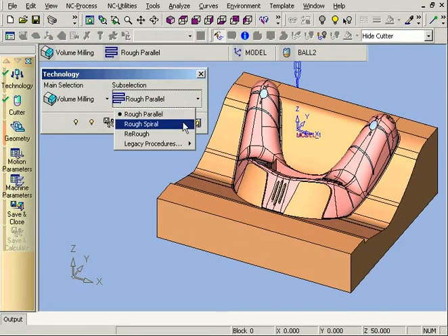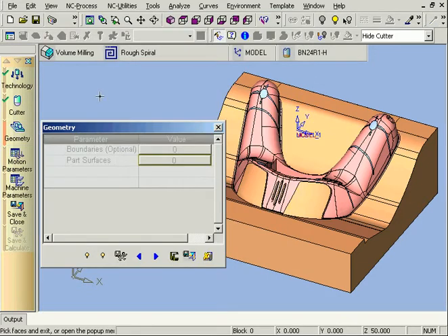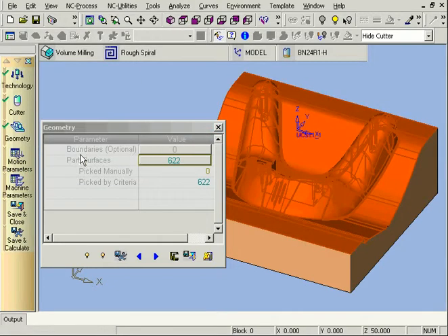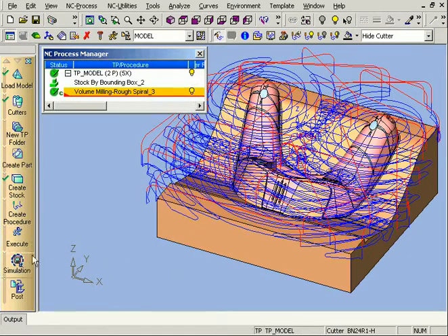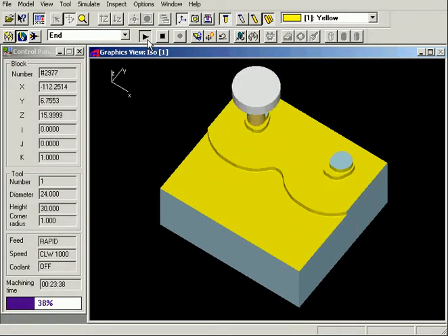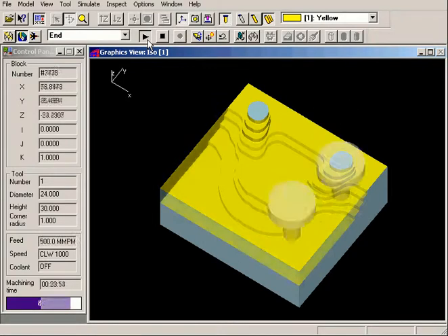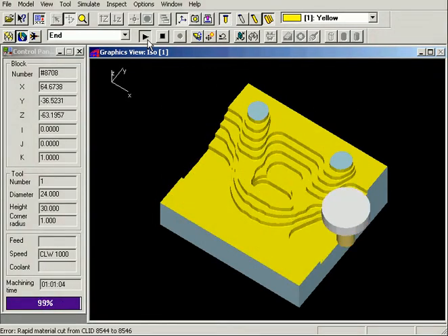The example shown here is rough machining of the entire part. This option allows the system to optimize the machining strategy. Alternatively, it can be controlled by the user. The next stage is simulating the resulting toolpath. Here, simulator and verifier display the material removal process and the resulting part. Local modifications, including trim, move, project, and delete, are applied.